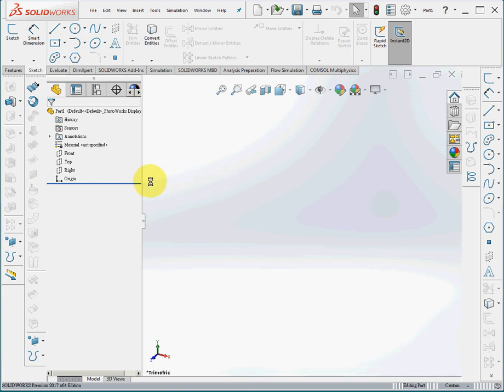In SolidWorks, there are the XY plane, XZ plane, YZ plane, origin, and the reference frame. For example, we have X direction, Y direction, and Z direction, and also the origin. In 3D modeling, the most important thing is that you know whether you are in 3D space or in a 2D sketch. So this is a 3D space. We can choose a plane and enter sketch mode.